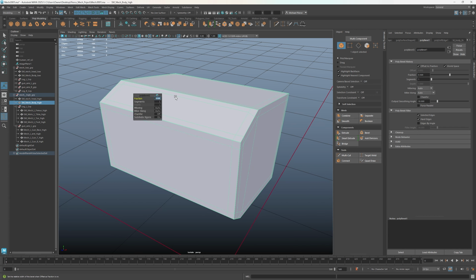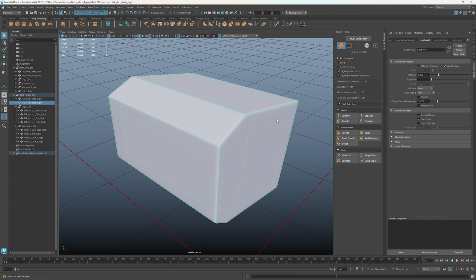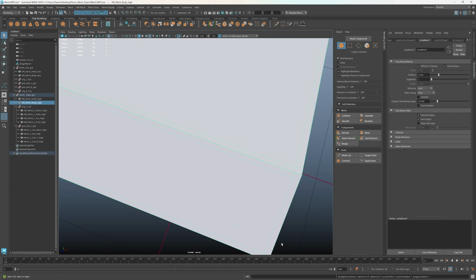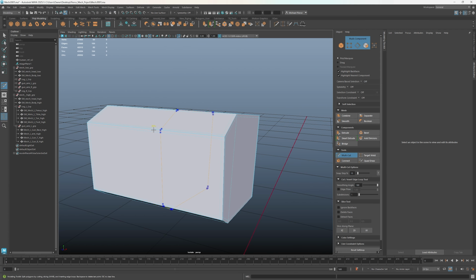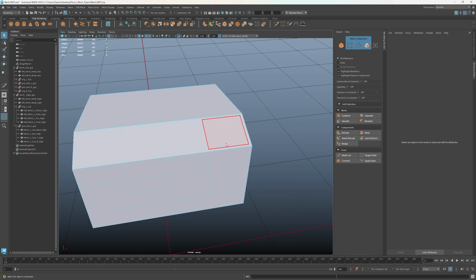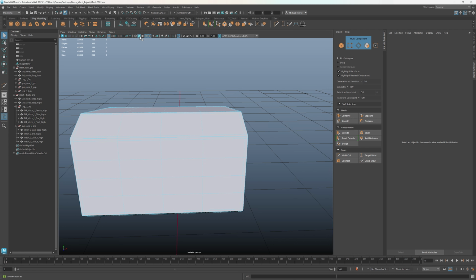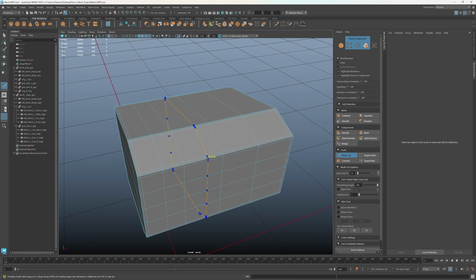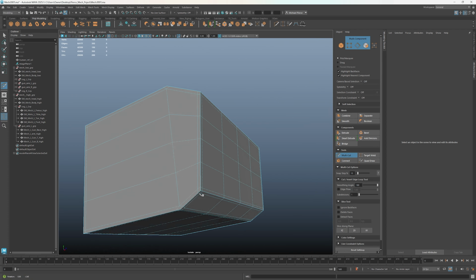Now I'm going to do like 0.1 and see what it looks like when I hit 3. I might do 0.2 just to see, because ultimately you don't want it to bevel too much on that, but this also needs to be divided up nice and evenly, especially if I were to bring this to ZBrush or something as well. I'm going to hit Alt-5, or in fact, I'll turn it on default shading. That way we actually can see things properly.